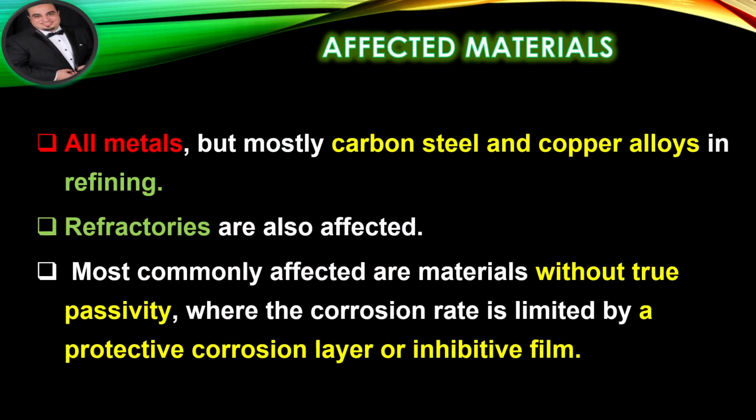Affected materials. All metals, but mostly carbon steel and copper alloys in refining. Refractories are also affected. Most commonly affected are materials without true passivity, where the corrosion rate is limited by a protective corrosion layer or inhibitive film.